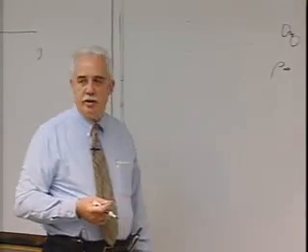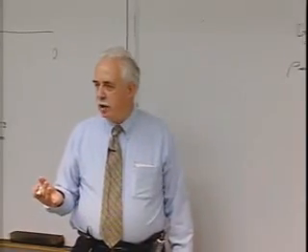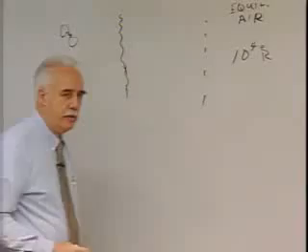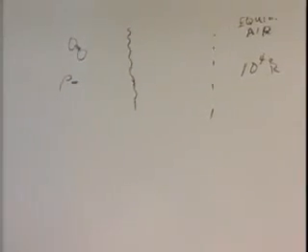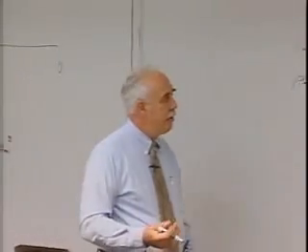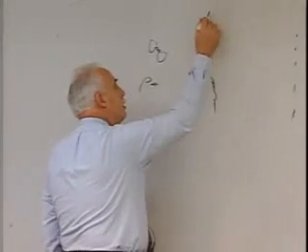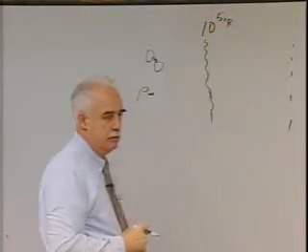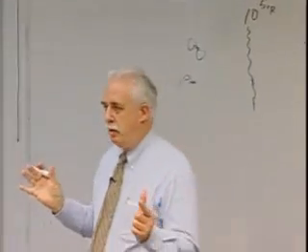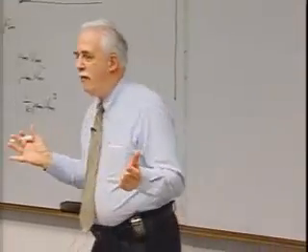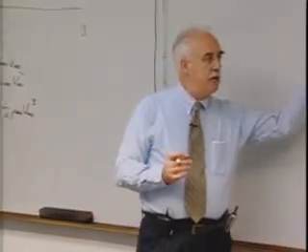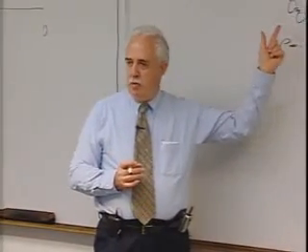Go through a shock, the density ratio is only a factor of 6. Here, the density is 15 to 20 times free stream density. And the temperature goes to 100,000 degrees Rankine if it just stayed as a molecular gas. Now, in fact, that temperature has no meaning other than if all the energy went into translation and rotation, that would be the temperature.